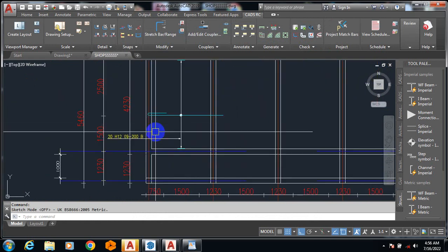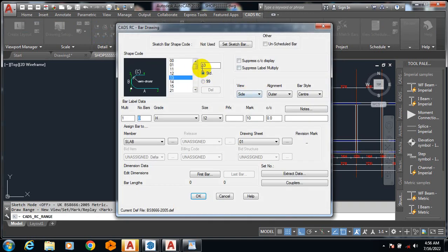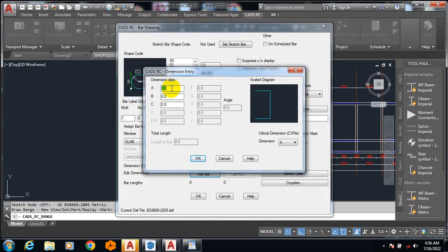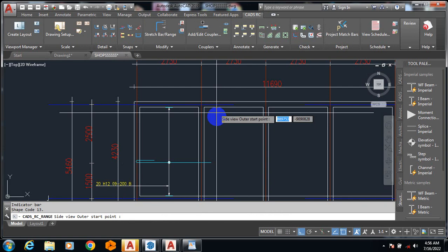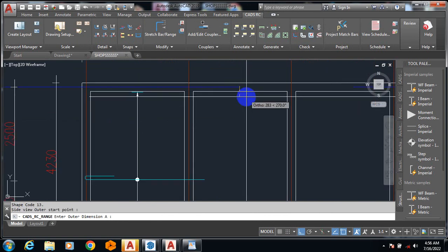Okay, all right. So let's say I have this now, and I click here, and I say 5 meters, for example, and then here I have 110, and then here I have 450. I'm just going to type in 450, and I click on enter, and I click on OK. It actually gives you your bar bending schedule, your quantity table. It gives you all of that. That's one other great thing. As we are doing this right now, it is generating that for us already in the background, so we can view all of that.